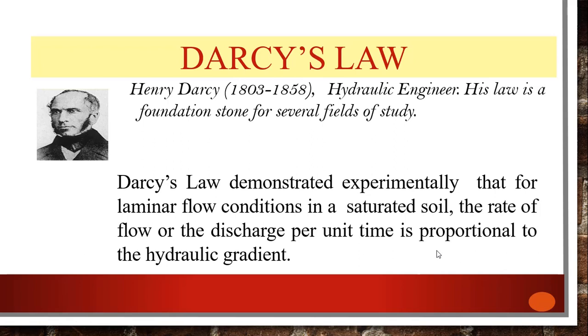Darcy's law. Henry Darcy was a hydraulic engineer. His law is a foundation stone for several fields of study. Darcy demonstrated experimentally that for laminar flow condition in a saturated soil, the rate of flow or the discharge per unit time is proportional to the hydraulic gradient.